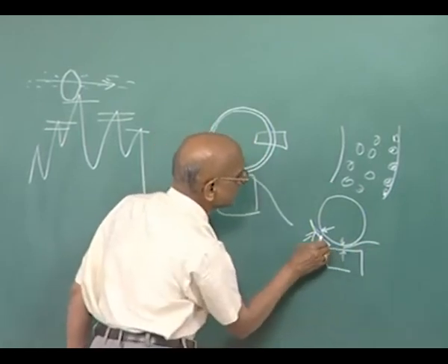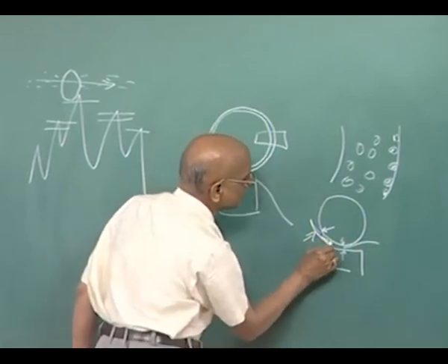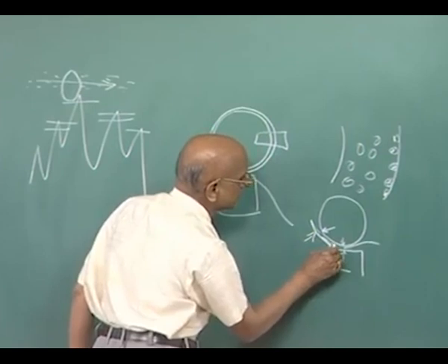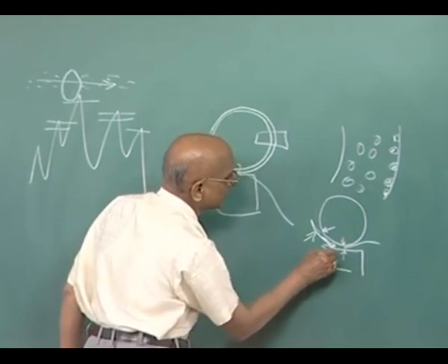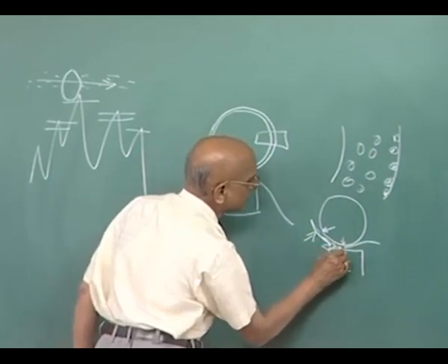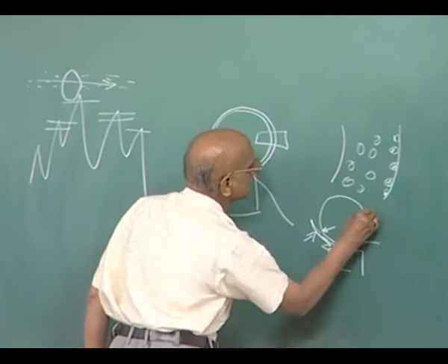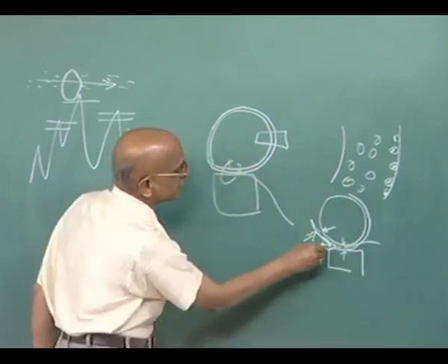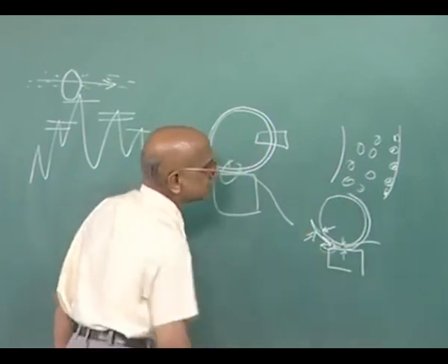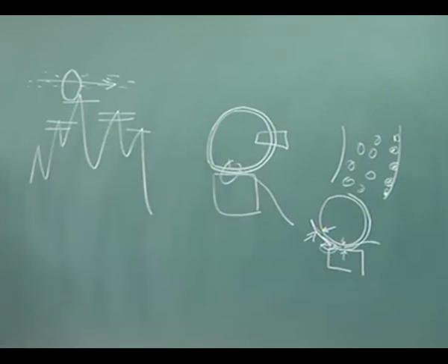So, this squeezing will take place, the fluid will be squeezed all over here, and then it will be moving like this. When this squeezing takes place over here, it creates additional normal force on the abrasive particles. Process parameters of magnetorheological finishing process.